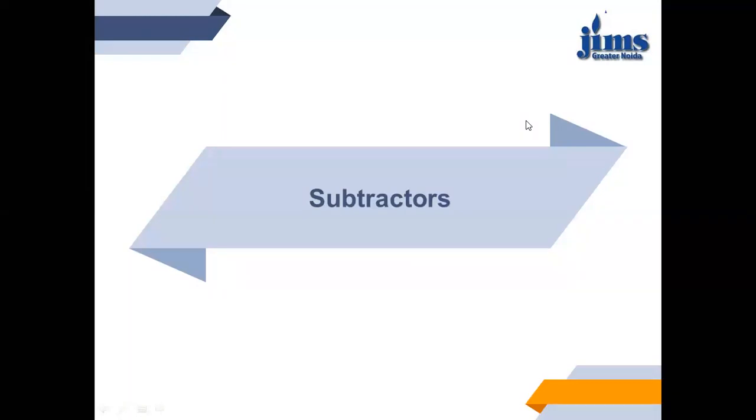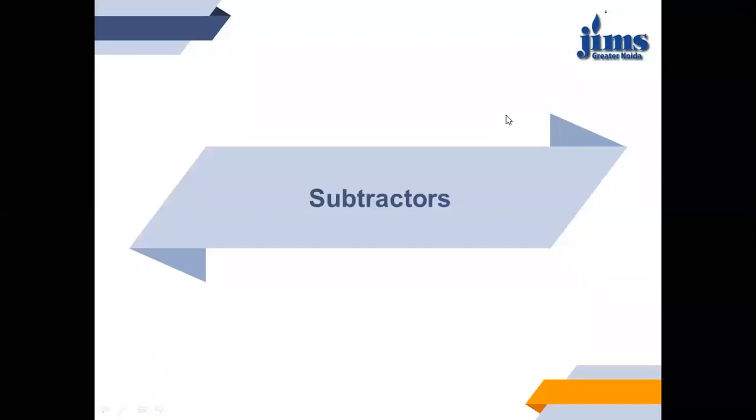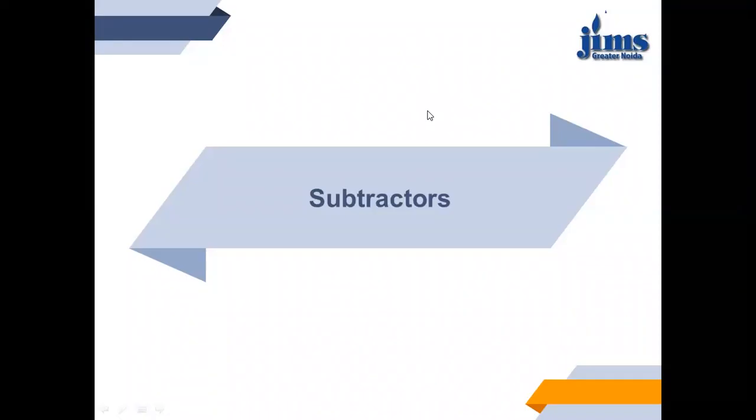In the analysis process, we are given a schematic or a circuit, and we have to find out its Boolean expression for the output, and we have to construct the truth table. On the other hand, when we have to design a combination circuit, we are given some specifications, out of which, first of all, we have to find out the number of inputs and number of outputs. The relationship between input and output is given in the specifications, and as per the specifications, we make a truth table. We solve the truth table to find the optimal SOP or POS term. Then we implement the circuit with the help of the basic gates.